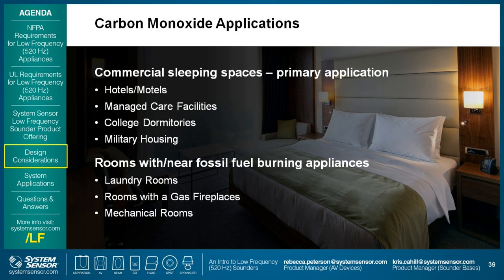The next requirement, effective January 1st, 2015, ties low frequency and carbon monoxide together. So not only will you be required to do the temporal 3 in a low frequency tone, but also you'll need to have a temporal 4 device in the room. This is why it is important that the B200S-LF offers a temporal 4 tone. Not all devices do this, so make sure you have the pattern you need for your application.